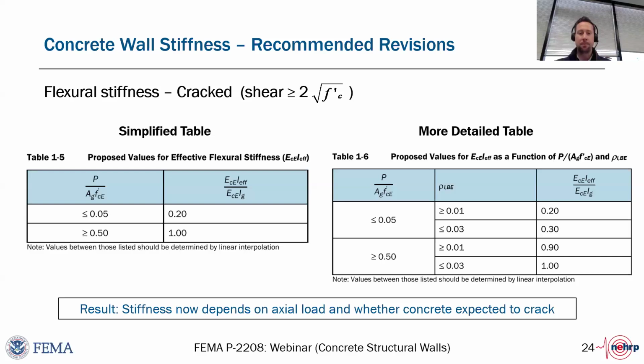That's right. Okay, so a general question about shear: is the dynamic shear amplification factor omega sub v the same as in 318.19 for consideration of higher modes? Yes, it's intended to be the same. At the time of the consensus process, and granted, this webinar is more about the technical recommendations that inform some of that, the technical recommendation was really, hey, do the same that was recommended in ACI 318 because there's no reason that they should be different conceptually.